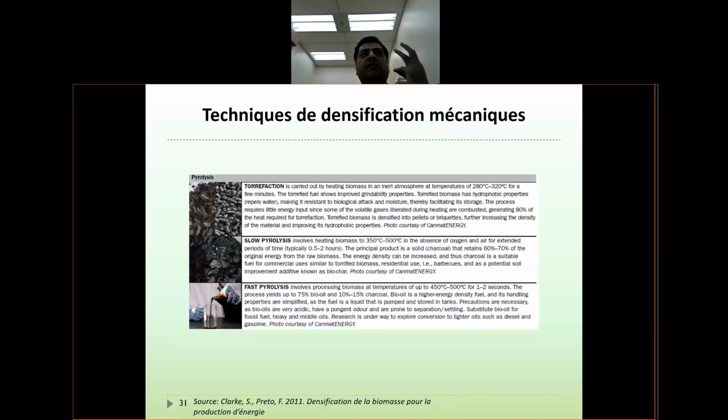We have bulk density, and the bulk density itself has two types: density at minimum fluidization, or aerated bulk density, and tap density, which means that if you have a group of particles, you just tap the vessel so all the air is out as much as possible, and the particles get as close as possible.